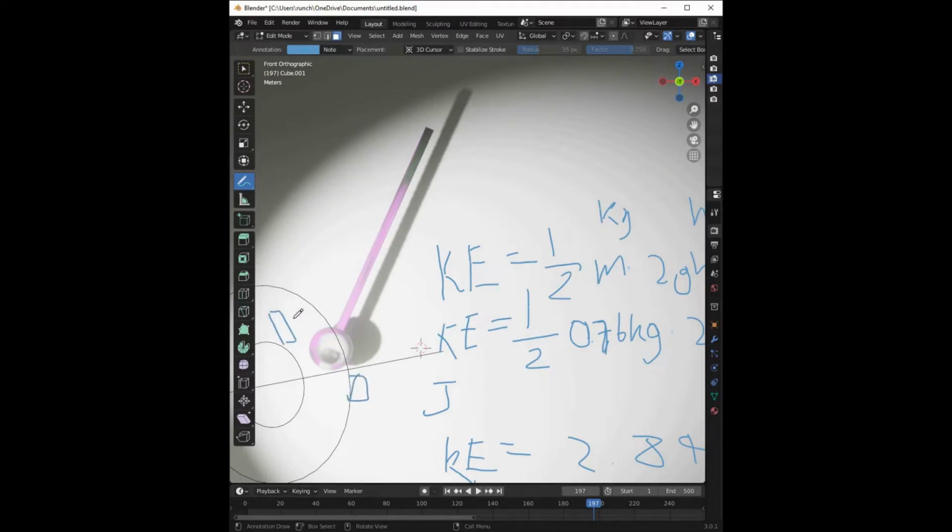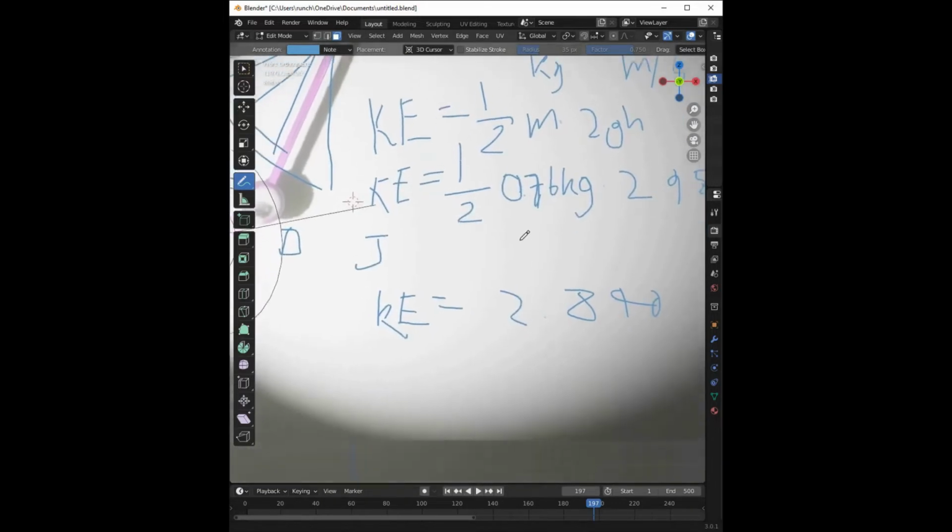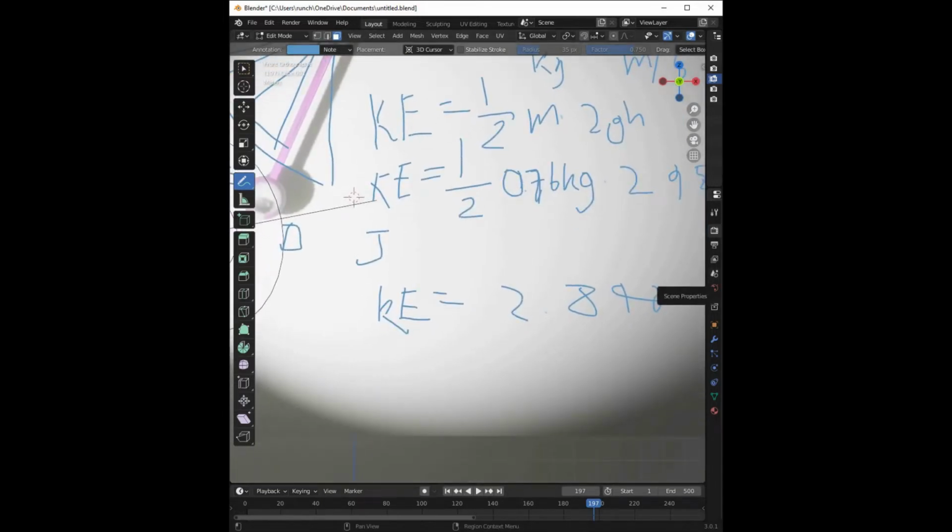So when the impact test sample gets struck by the pendulum, let's just say there was a broken piece here, and it just got blown off by the pendulum. It absorbed a little bit of impact from it being a solid piece of plastic in my case, and that will show how much it swings back up on the other side. So in my build, I have a dial, and it pushes it up, and it will only stay at the peak of its swing on the other side. And that way I have a piece of paper here, and it will show me how many degrees it swung to, and then I'm able to see how much of an impact the piece of plastic absorbed in joules.